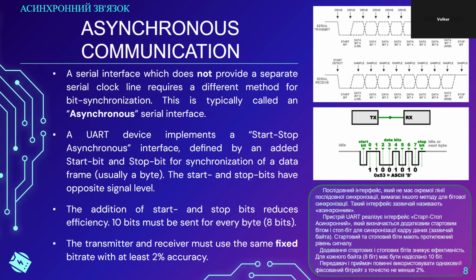Same reason, except in this case, a divider by 12 is involved because the 8051 has a 12-division machine cycle clock. So when you see those strange crystal frequencies, usually the reason is that the system is trying to get an exact specific bit rate for asynchronous communication, right.